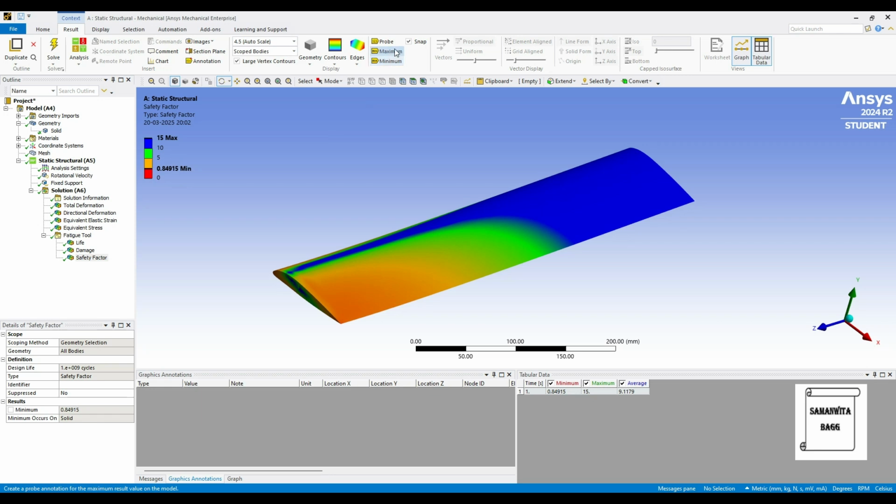As you can see here, if you choose probe, you'll get these values. See, it is between 0.8 and 5. And then again, it is between 5 to 10 in this green color zone. As you can see, you can run the probe over it. And in this blue zone, if you move your probe, it is 15 or 14 point something, 13 point something. So it is 14.993 as you can see. So it is close to 15. So that's how you should be reading these values.